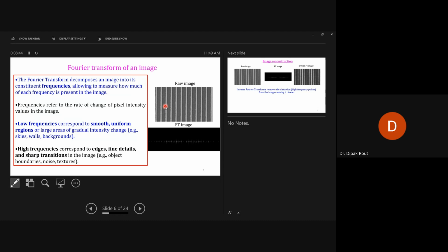For each pixel, depending on how much red, green, or blue content there is, they add up to give us a grayscale image or a white scale image or even lower intensity images. So if we have pixel information and the intensity of each pixel, then we can go about doing the Fourier transform and bring out the exact information pixel-wise. And then further, we can reconstruct that image from the raw image.